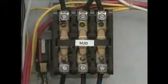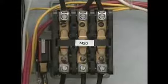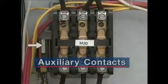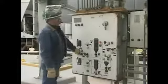An AC motor controller typically has 3 sets of contacts, one set for each of the 3 phases of power in the AC power circuit. A motor controller may also have additional sets of contacts called auxiliary contacts. Auxiliary contacts are usually attached to the armature and operated by it. These contacts are used to perform auxiliary control functions, such as providing current for indicating lights, like the ones used to indicate whether a motor is on or off.